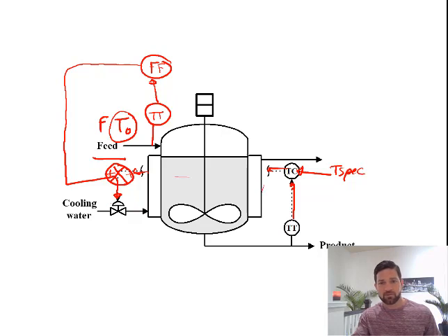If the primary control loop is at its specified value, but the temperature of the feed increases, we can accommodate for changes in the increased temperature before the process changes. We know an increase in temperature will eventually affect this process, but if this temperature increases, immediately the feed forward controller will have this valve open to start cooling the system more before the product temperature changes too much.